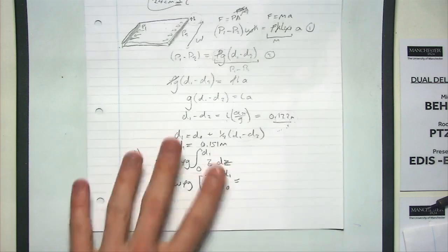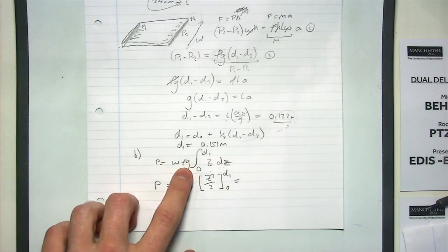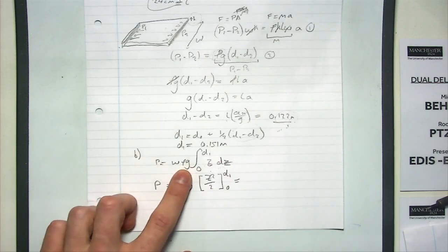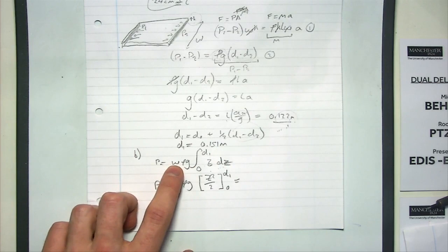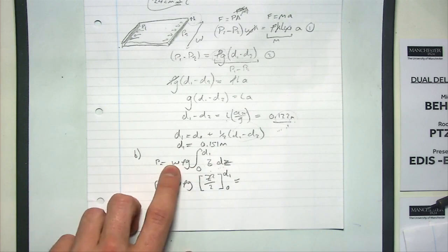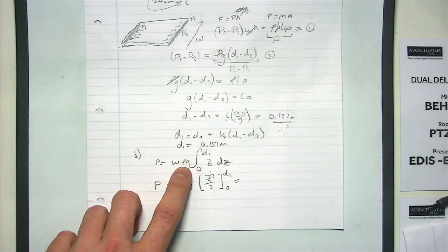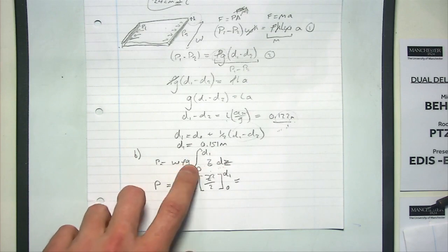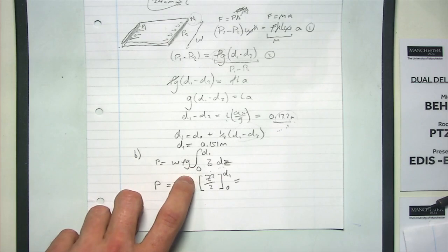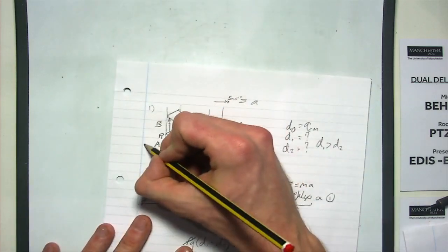Okay, so this value here, the rho g, you can sort of interpret as the weight of the fluid, right? So we're saying lots of tiny little bits that wide and that much weight of the fluid on top of it. But as it goes deeper, it multiplies the weight of the fluid by a bit more, so it adds a little bit more each time. Yeah? So z is the depth? Yeah, z's depth.